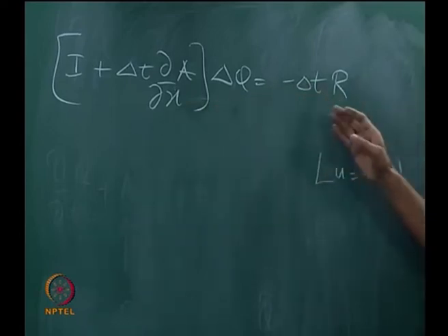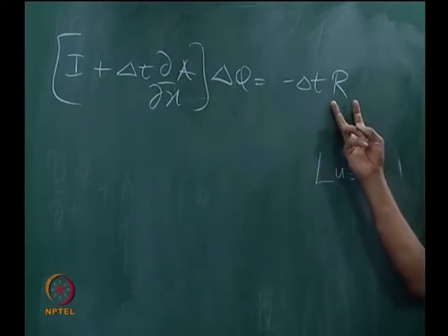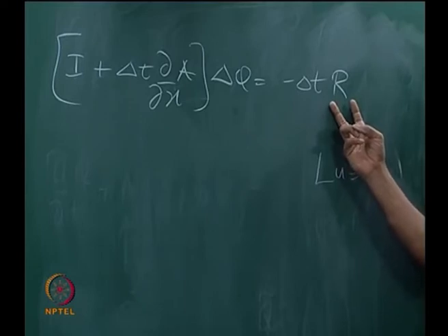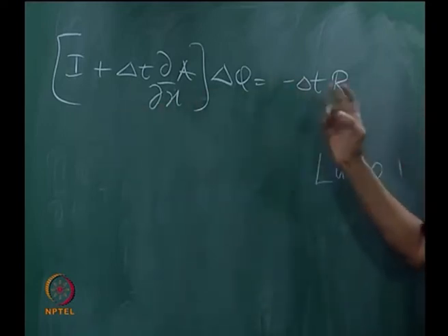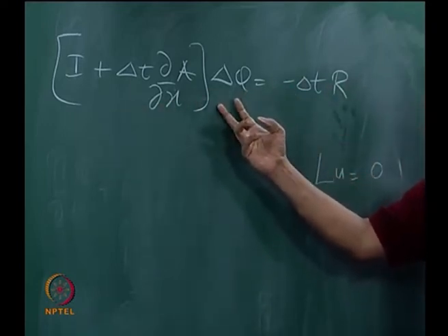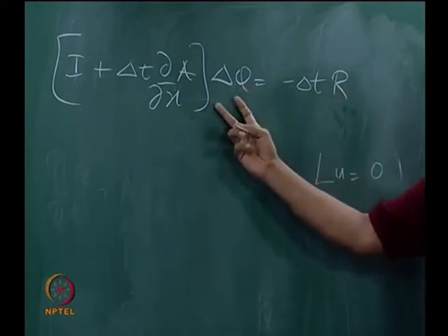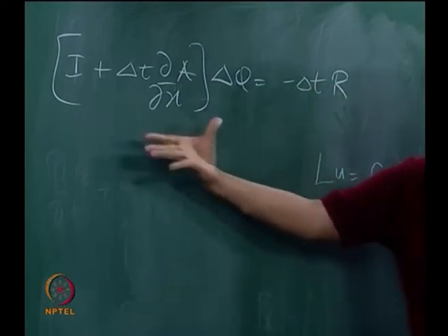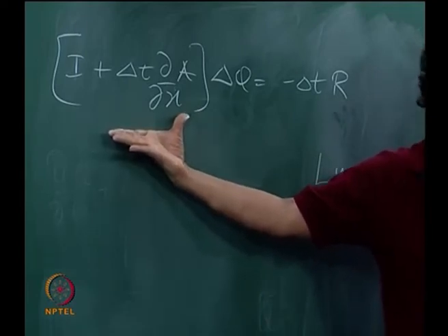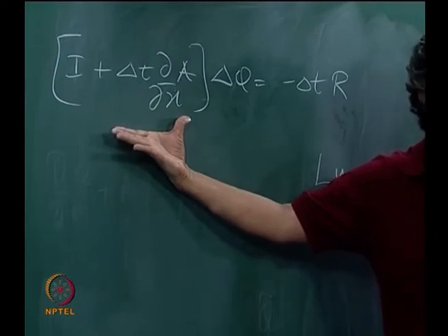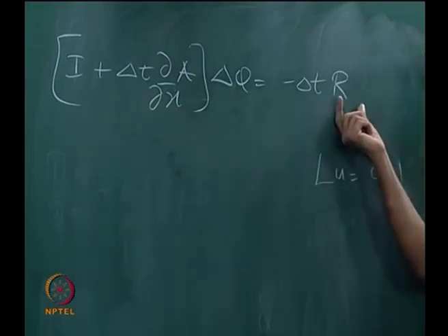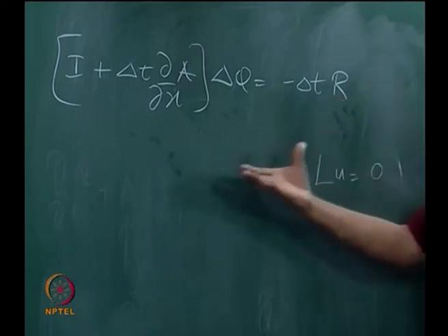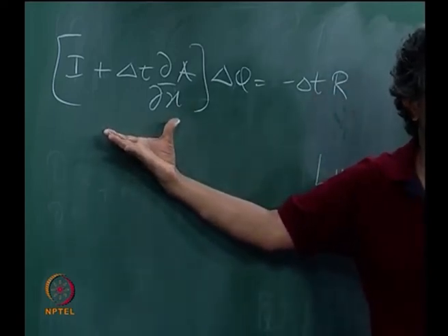The big thing that we want to take from here is that this R will determine if you reach the solution or not. If the residue is 0, your current state is correct. If the residue is not 0, your current state has a problem and needs to be corrected. You can solve the system of equations to determine the correction. If the residue is 0, the correction is 0, as long as this is not singular, it can be anything, and therefore it is possible for us to choose something that will make the convergence faster. That was the other deal that we had. So we do this carefully because this determines when you reach the solution. You do this carefully because that will determine how fast you get to the solution.